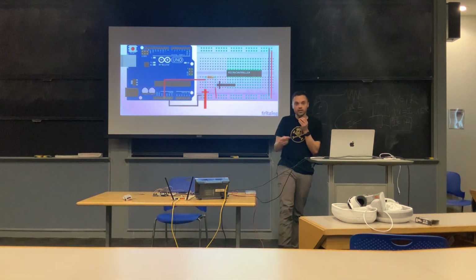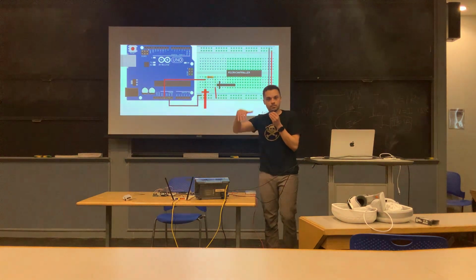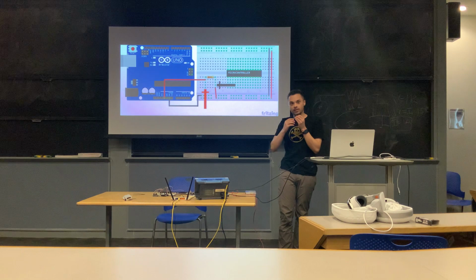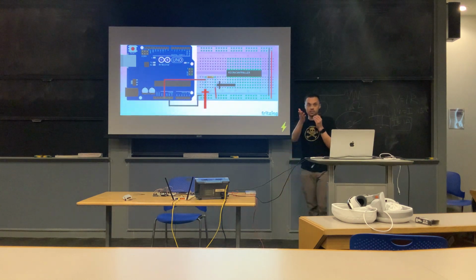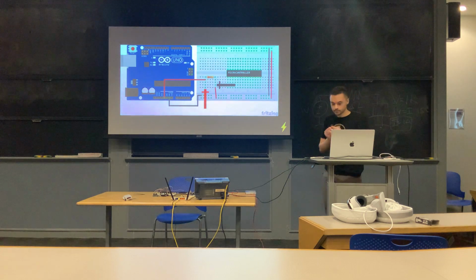But if you were to do this for a real chip that's very sensitive, you'd probably want some bypass caps on the other side and maybe increase your voltage just a little bit to compensate. But yeah, excellent question. The answer is it kind of depends, but for this setup, it works.